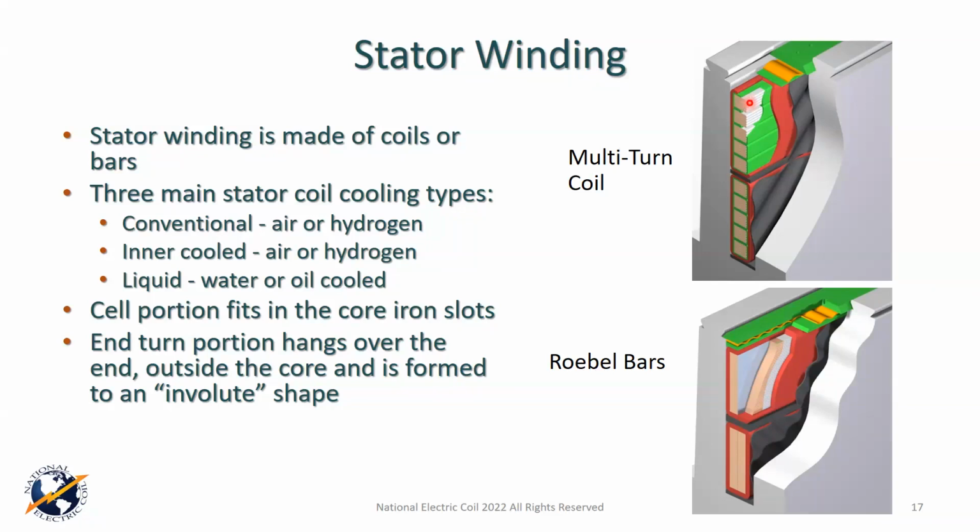Now, in applications where you have a very high voltage stress in the design, and this is where the design engineers would calculate and pull this all together, they can go to a material that's a little more robust from an electrical standpoint, and it's usually called enamel. Enamel can be put on, and you can put on a single layer or a double layer of glass on top of that. Enamel is a little bit thinner, but it's much higher dielectric, and it's quite helpful if you've got high voltage strand to strand.